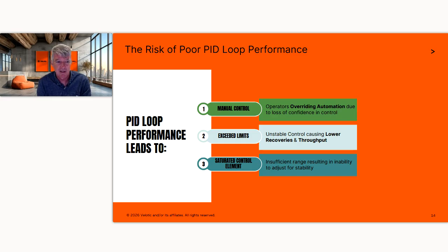Another thing that also happens with PID loops, and sometimes you have to see this, is that I might have equipment out there, like sensors that are out of calibration, or the manipulated variable, like a valve that's too small, so that even if I open that valve up 100%, it can't feed enough gas to keep 60 PSI.